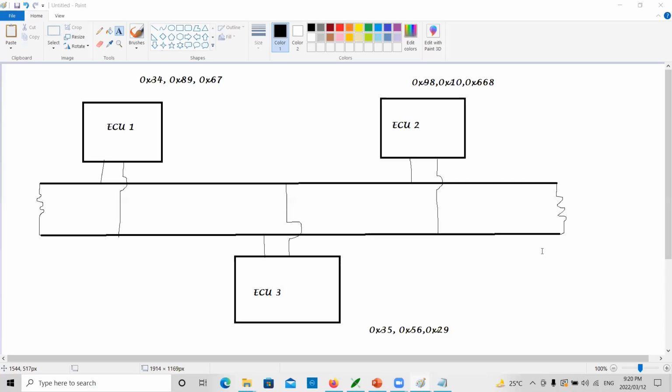In a car, we will have multiple nodes. Yeah, you can have, but no car will have 100 nodes and all. Every ECU can have hundreds of signals, thousands of signals. That is not a problem. As an ECU capable of transmitting CAN messages, that can go up to 32. That is also a practical scenario, but theoretically, there is no limit.